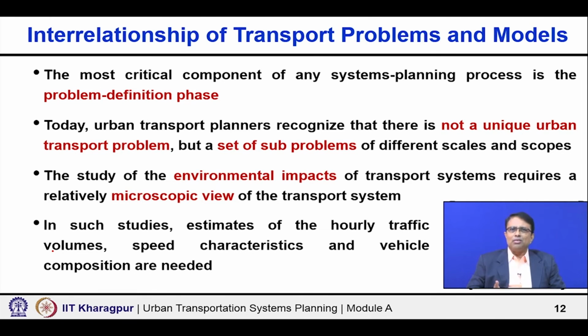It depends on what level you are developing your model, but some of these things you will definitely require. And you also require the vehicle composition, because not every vehicle will emit the same, right. It will vary depending on whether it is a petrol vehicle, whether it is a diesel vehicle, whether it is a bigger one, whether it is a smaller one, whether it is Euro 3 or Euro 4 or Euro 2, different emission standards are there. So you need actually vehicle composition.